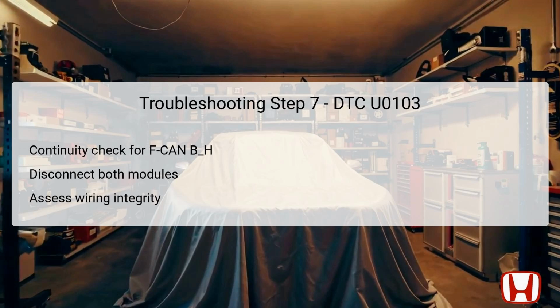Ensure the vehicle remains in the off mode while both the SBW shifter control module and TCM connectors are disconnected for an accurate continuity test. Check the continuity between test point number 9 from the SBW connector and number 7 from the TCM connector.